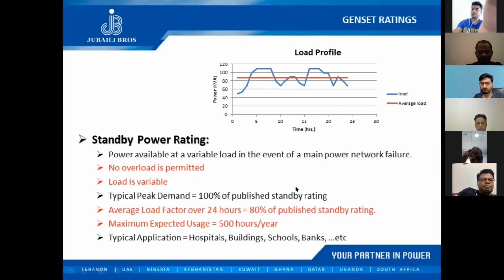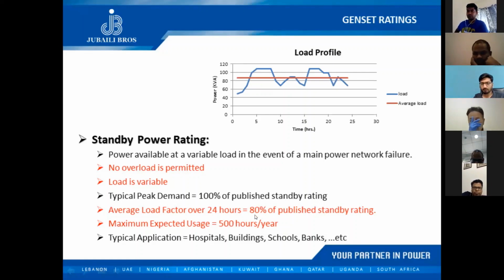The answer is yes, we can. Abdul Karim is saying that it's 1 hour every 12 hours, but that is related to prime ratings. In a standby rating, I can use my genset at 100% of the published standby rating for several hours, given that I do not exceed 80% as an average over 24 hours.